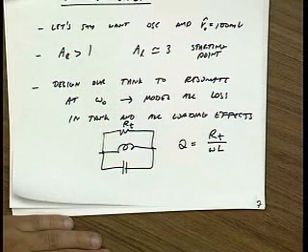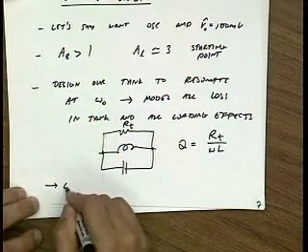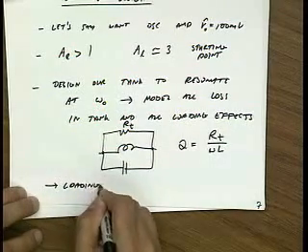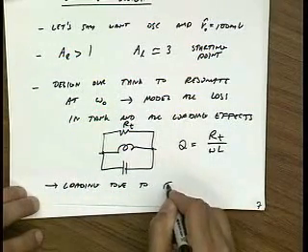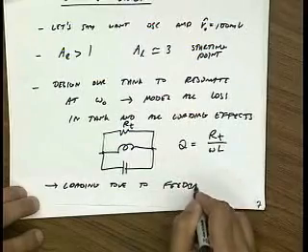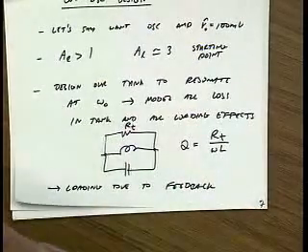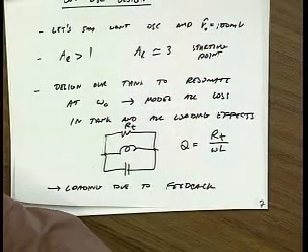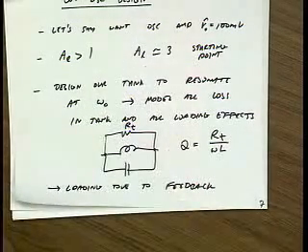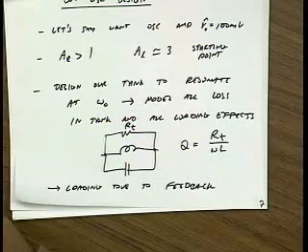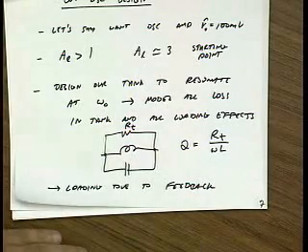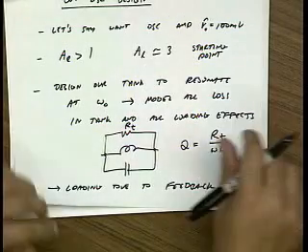And if you have feedback, as we saw last lecture, you have to be careful to include the loading due to feedback. So in the case of the transformer feedback that we looked at last lecture, the input impedance of the transformer appears at the tank through the transformer winding ratio squared. So you have to make sure you include that. Okay. All right.